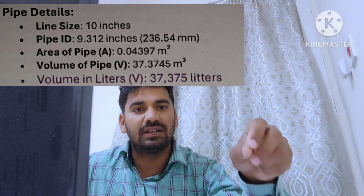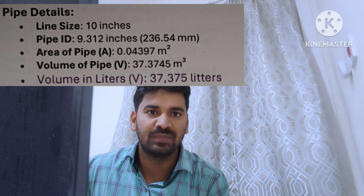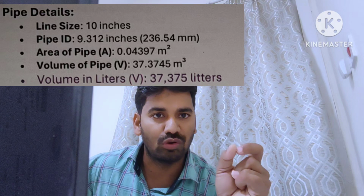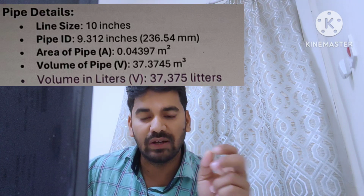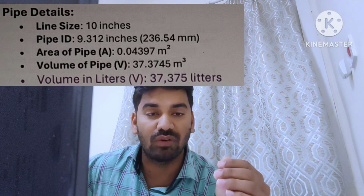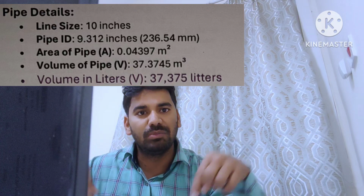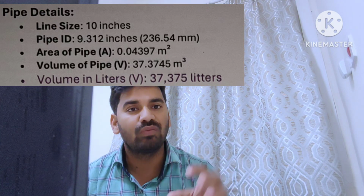So basically this is the detail of the inside of the line and how much water is required for the testing. There are two major things: how much volume, and after that how much water is required for the testing. If the volume is 37 cubic meters, that means the water required is 37,000 liters, because 1 cubic meter means 1000 liters. So in the overall line, 37,000 liters of water is required for filling and pressurizing.